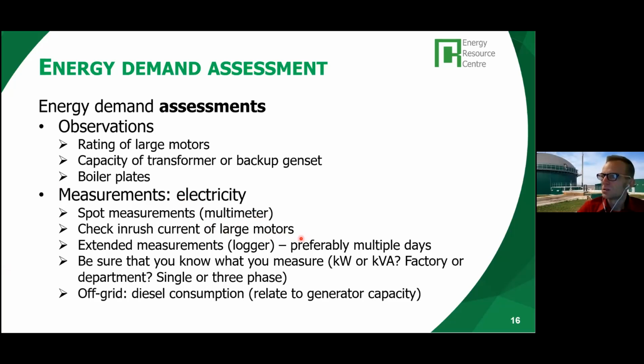So that's a data logger. When you do measurements, it's of course very important to know exactly what it is that you're measuring. On one hand, that's knowing whether you're actually measuring the active power or the apparent power, kilowatts or kVAs. Like I said, if you're using a clamp-on meter, just measuring the currents, then the only thing that you can calculate afterwards is the kVA.